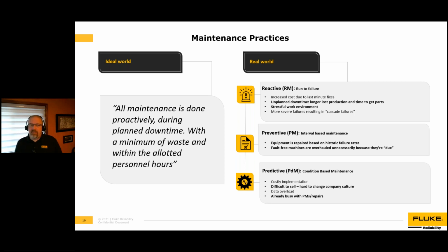Condition-based or predictive maintenance is sometimes referred to as reliability-centered maintenance. Using predictive maintenance, the appropriate time frame for repairs is determined by the machine's actual condition. Those repairs are done using precision techniques such as laser shaft alignment, and after the work is completed, it's verified for accuracy.